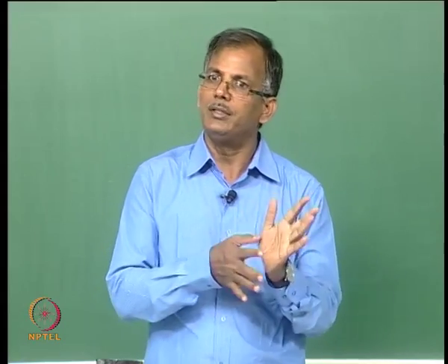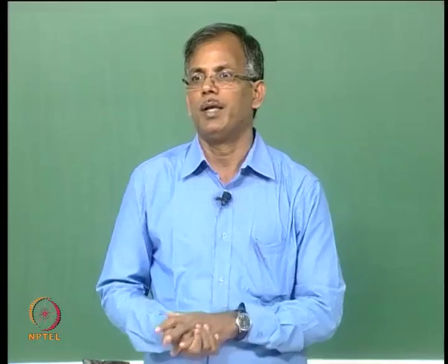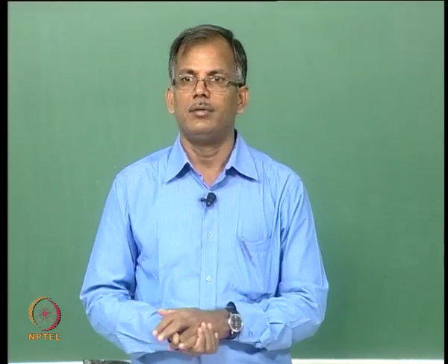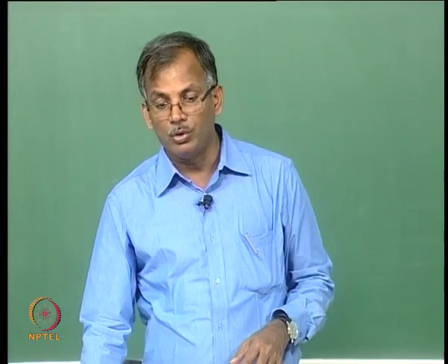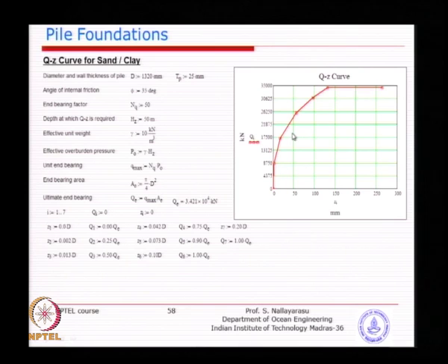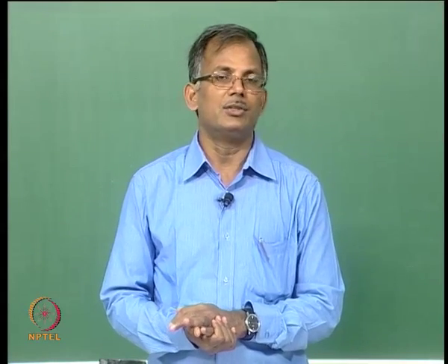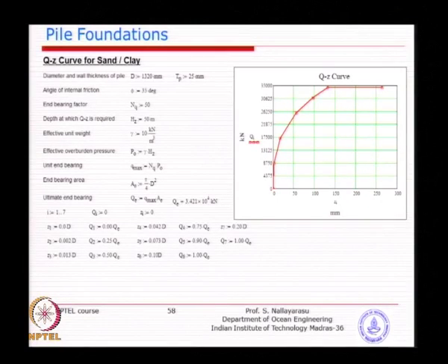So, with 5% you may think, why do we need to go to non-linear, why not do a linear relationship and simplify the design process. Whereas here we will not be able to do that, because the capacity we lose is almost another 100%, which is not going to be very good. So that is why historically we use nonlinear pile soil interaction analysis, because good soil strength is very rare to come by. So that is why we have to follow this principle.